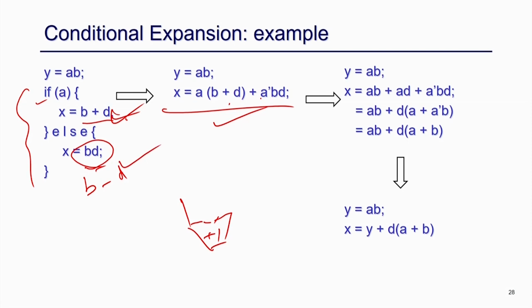I can just take B and D, and I have only one control signal that will decide whether plus or minus, right. Then it will do either B plus D or B minus D based on A, right. So, if it is A, this will be done like this, right.